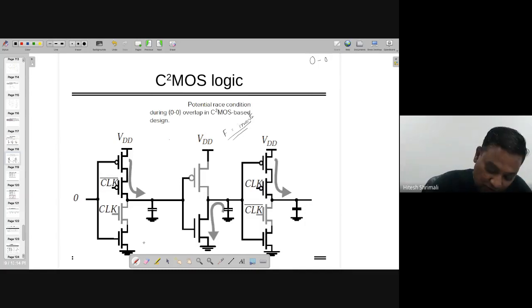Let's start with 0, 0. If it is 0, 0, then all these transistors which I made here are going to be on. Now look at this. When input equal to 0, VDD is available here, right? VDD will make this transistor on, and this is available at 0. 0 will make this transistor again on, right? And the output is equal to VDD. You see?